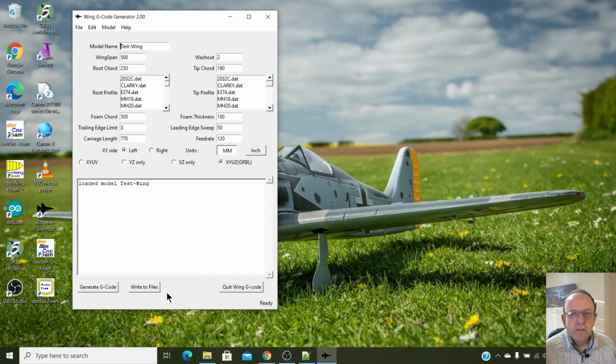I'm working on it and I've got it working, but I need to do some more testing. I'm working on what's called a G93 mode, and that's to do with feed rates, and it works really well on foam cutters. It originally comes from rotary axes on CNC machines, but it works really well on foam cutters, especially if you've got a root and a tip where there's a big difference in the size, or you've got a swept back wing. I had some experiences when I was using Linux CNC without using G93, one of the axes would go like crazy trying to keep up with the other one, and it was all to do with this feed mode. So yeah, and I managed to get it sorted. There was a very clever guy on the Linux CNC forums that came back to me with a Python script to load in the Linux CNC, and it worked brilliantly. And the G93 that I'm putting into this is mostly based off of that as well.